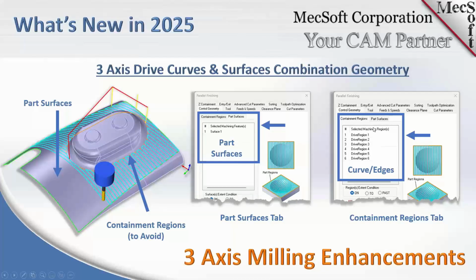And then over on the containment regions tab, we've added these curves, as you can see in orange here, that go around the base of this feature. So the result is parallel finishing will only take place between those two areas, from the perimeter of the surface, and then stops at the inner curve region. If you have some complex features in 3-axis that you need to cut, this will come into play and help you out. A little bit more control in the 3-axis parallel finishing.